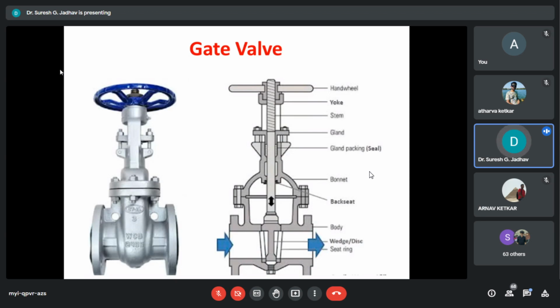The minimum hardness specified by the code for this material is 200 HB, that is 200 hardness Brinell. HB stands for hardness Brinell, 250 HB and 350 HB. Minimum differential between body and gate seats, the body seat being harder. Deposition of harder material like Stellite 6 is also done for valves used in special services.